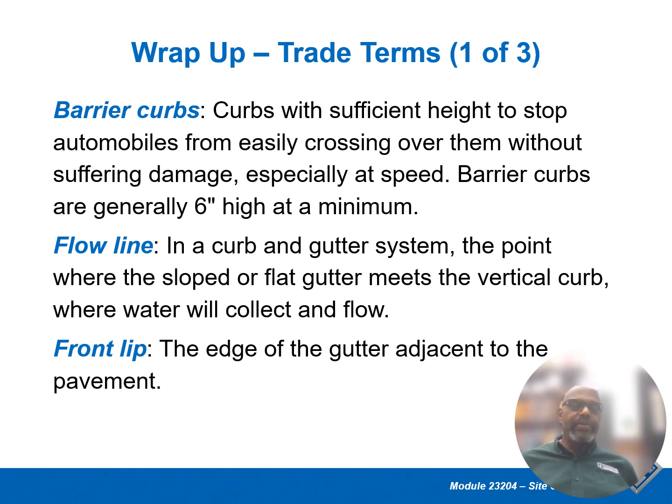But it might be a grocery store that will build a barrier curb. It's high, so a car cannot just drive up on the curb and go through a window or the wall. So it would be 6 to 8 inches high, sometimes even higher, 7 inches, where somebody could step up, but a car would end up damaging itself if it actually tried to go through it.